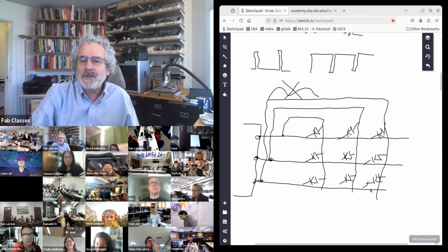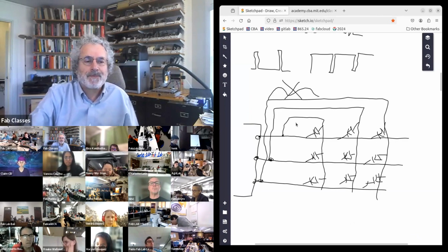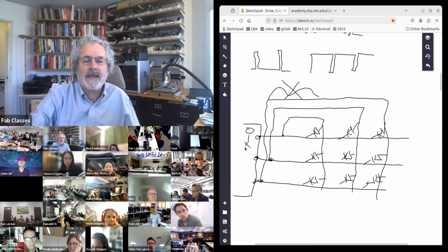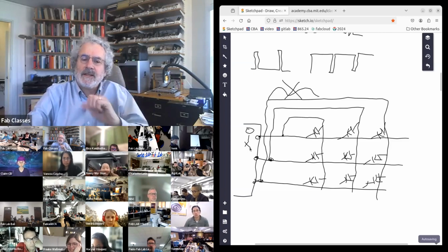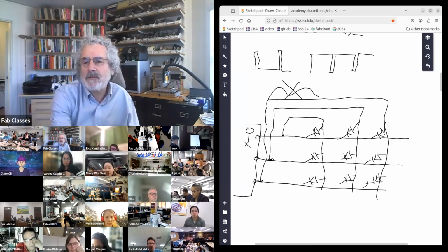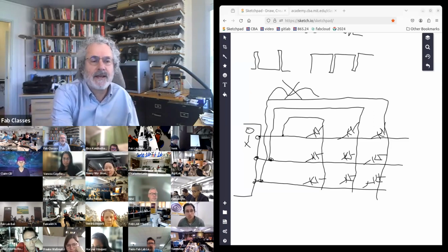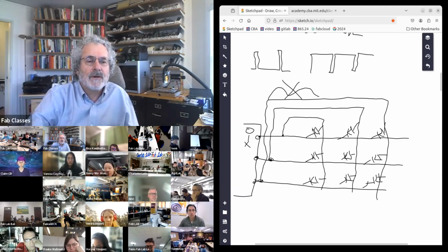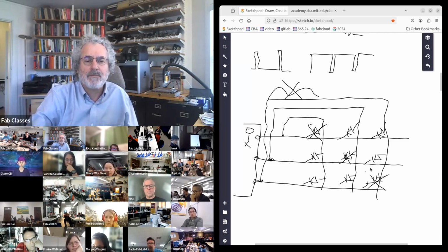So it's crazy. Each pin is a row and a column. Now, what makes this work is a pin can be off, it can be on, or it can be tri-state, which means it's disconnected. It's an input. So each pin can be either off, on, or disconnected. And so, first of all, the diagonal ones I can't use. So you don't actually put components there.